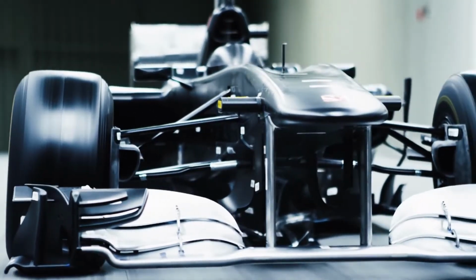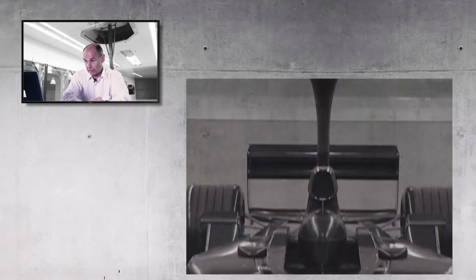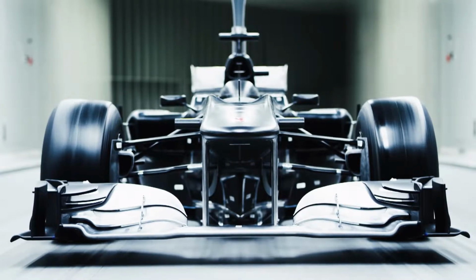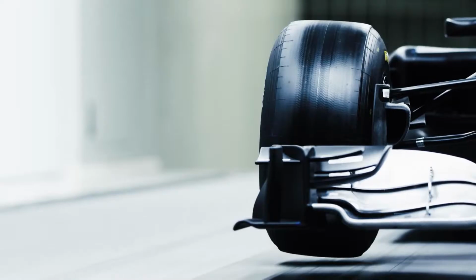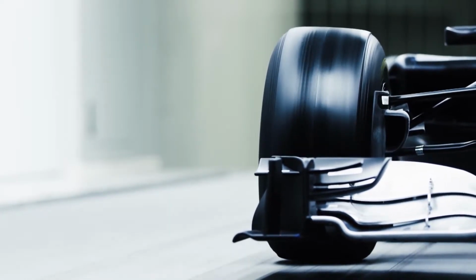We have wheels mounted on our model. I've worked with both wheels mounted on the model and wheels remotely mounted on arms, so that the vibration and the inaccuracy caused by the vibration of the wheels is not transmitted to the measurement systems on the model. But we found over time that the absolute accuracy of having wheels mounted on the model outweighs the slight measurement repeatability problems you have when the vibration of the rotating wheels just slightly reduces your ability to repeat a test precisely. And that's been achieved through experimentation. You try both systems, you see which gives you the best results. And now there is such importance placed on the aerodynamics of the wheel and how that changes the airflow around the car that I feel you really need wheels on the model.